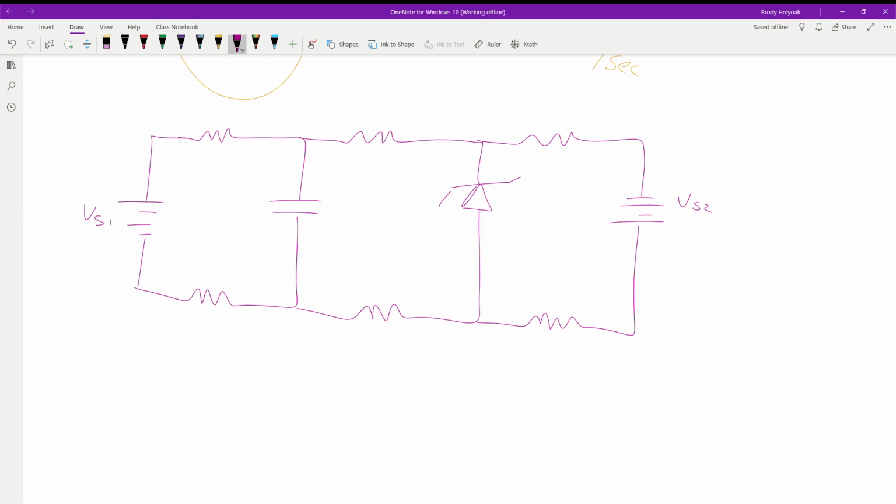So the first thing we need to do is we've turned the circuit on. We're going to measure it. What has happened in the circuit since we've turned it on? The capacitor has charged. So our cap is full. When our capacitor is full to DC, what is it? It's an open. So now it's an open.